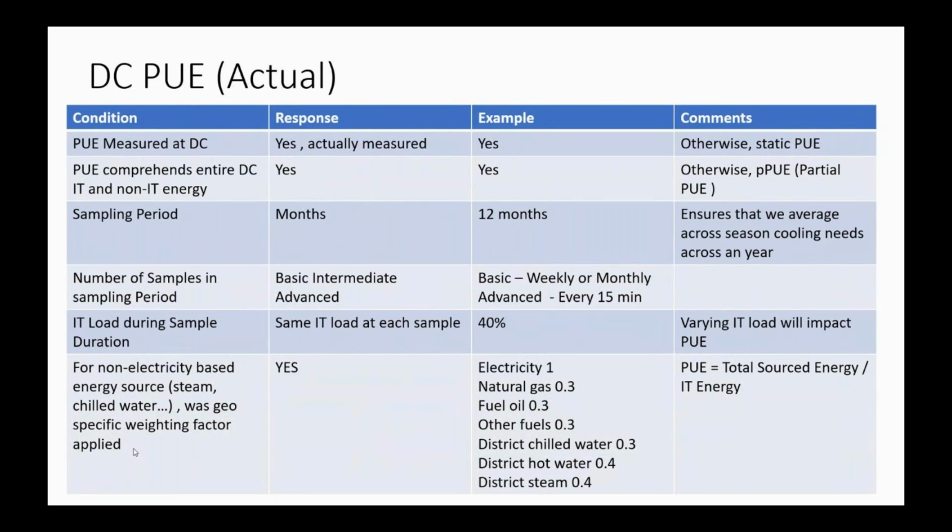However you get to that, the P part in PUE is ill-defined, if you will, because when they defined these things, data centers were at a pretty nascent stage, and you don't blame them for what they defined. But in our heads, we should not think of it as power, we should think of it as energy. Essentially, whatever the total source of energy you put in, the ratio of that to the IT energy is what PUE represents. So the total source of energy could be anything.